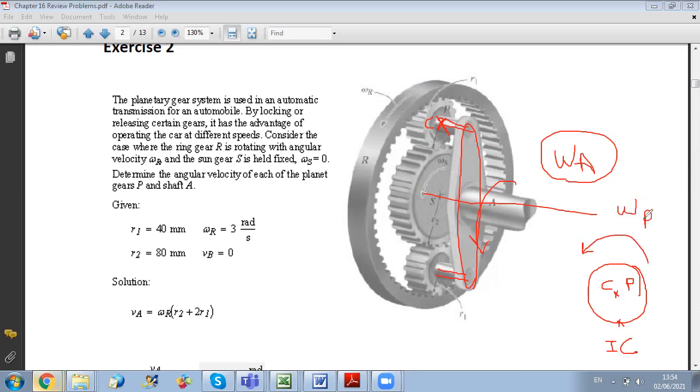So I know from the instantaneous center method that the velocity of C will be perpendicular to the distance joining C and the IC. For the direction, I can know it from the right hand rule. Because omega is counterclockwise, V should be to the left in order to have rotation in the counterclockwise direction.